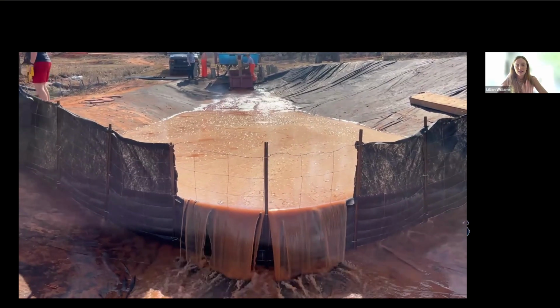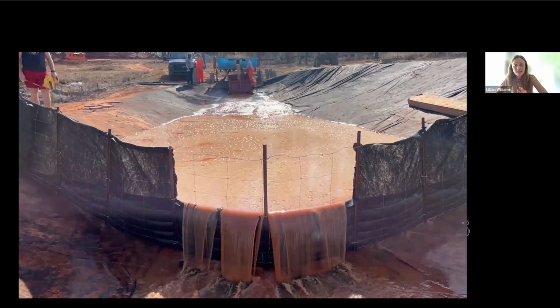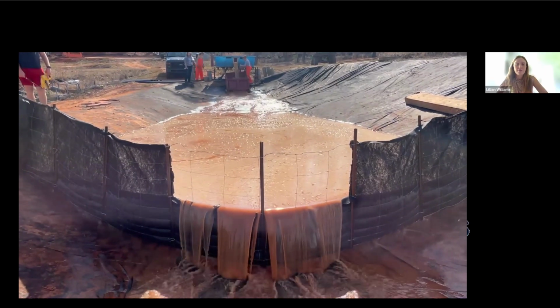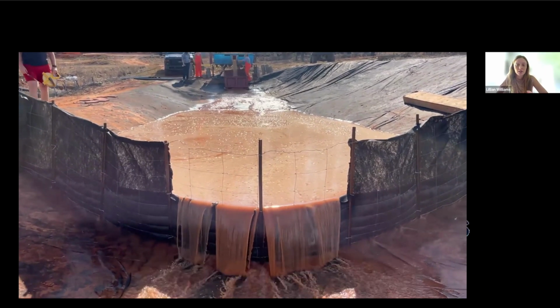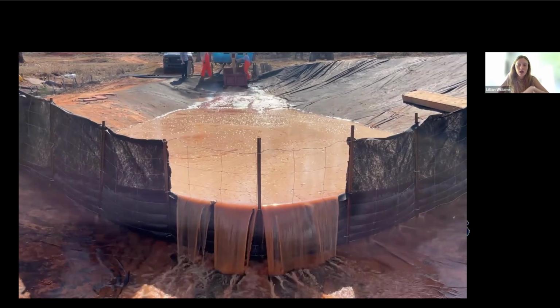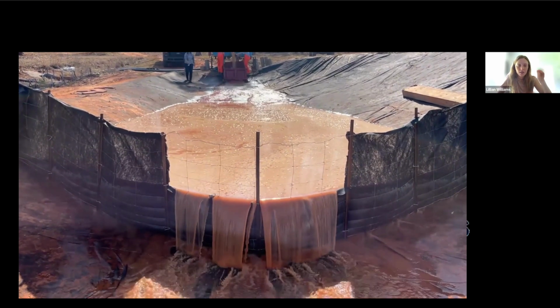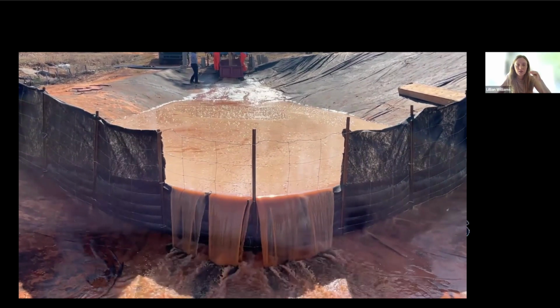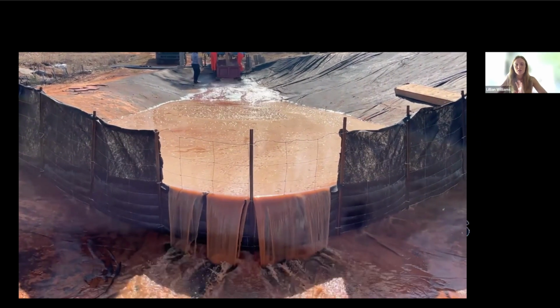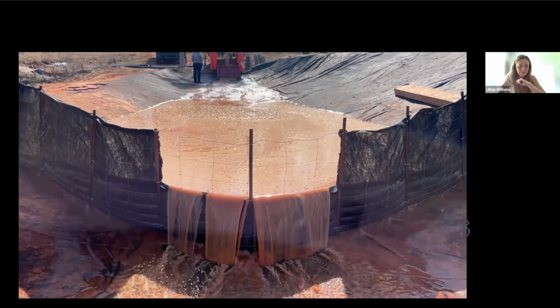The wire backing gives it that support. And this actually gave us 35 feet of impoundment, which is the most seen in any of our silt trap tests. And this was an ALDOT adopted silt fence for the ditch check. So we adopted what Alabama had done and used it in this Nebraska setting.